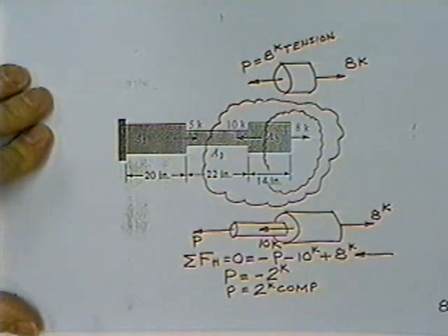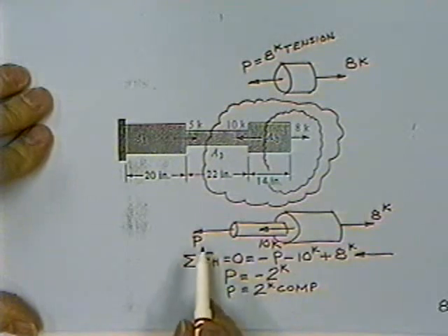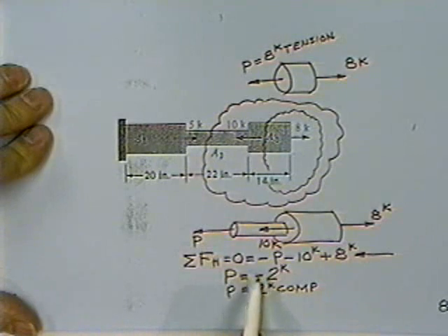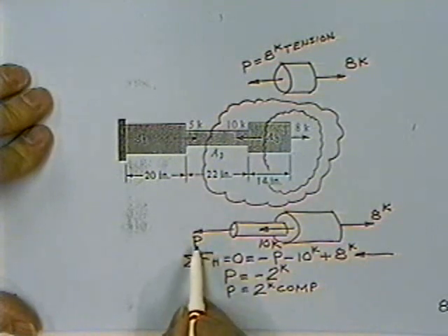Many times, like in this case, someone's in a hurry and they'll find that the load P is equal to a minus 2 kips, and it does look like it's pointing in the minus direction. They say, well, okay, I guess that's right. That's not what that means. The minus sign means it is not a tensile force, it is actually a compressive force.